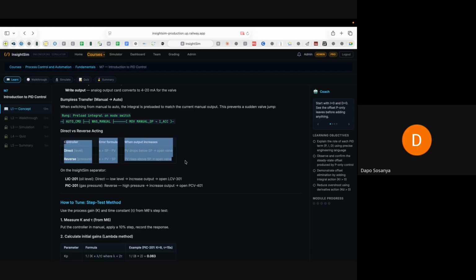In valves now, you have what you call FO and FC, that is fail open or fail close. And then in electronics, you have normally close, normally open. All of these things are similar concepts that you need to be able to resolve. They are not entirely intuitive, but you need to be used to their thinking, because these are the things you will encounter in the plants, right?